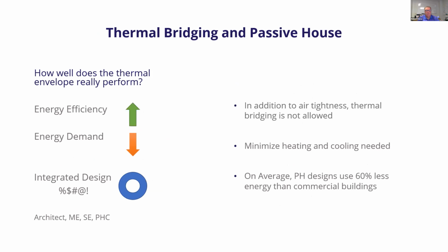So how does that relate to Passivhaus? Well, in Passivhaus, and I'm not an expert by any means, one of the critical requirements is to reduce thermal bridging as much as possible, because there are requirements in Passivhaus for the allowable thermal conductivity at interface and transition details, okay? And much like the Model Energy Code, 90.1 ASHRAE, by climate zone, there are R values and U values assigned that you're meant to meet for your wall assemblies. Now, those R values and U values, again, need to be the effective R values and U values, meaning they consider the effects of the thermal bridging.